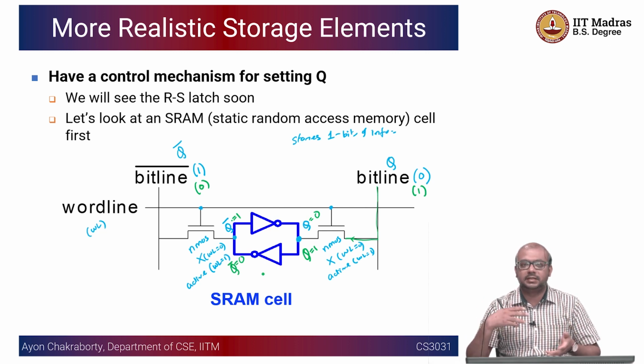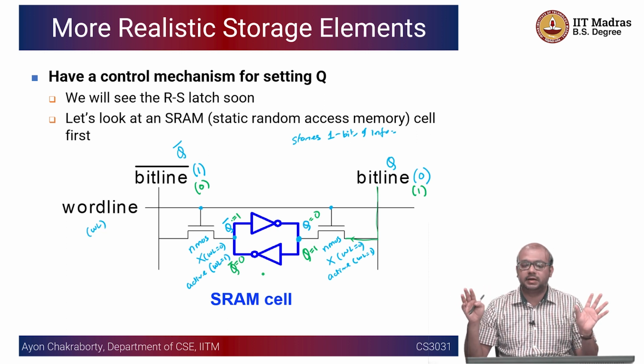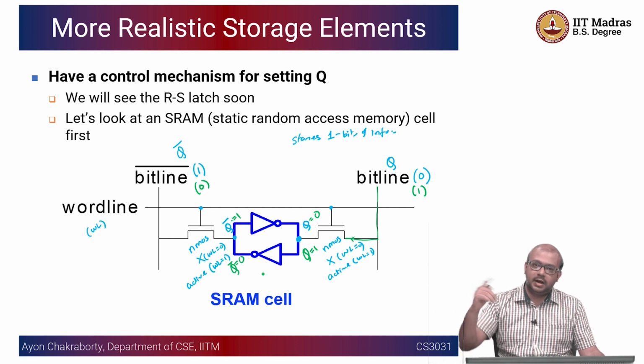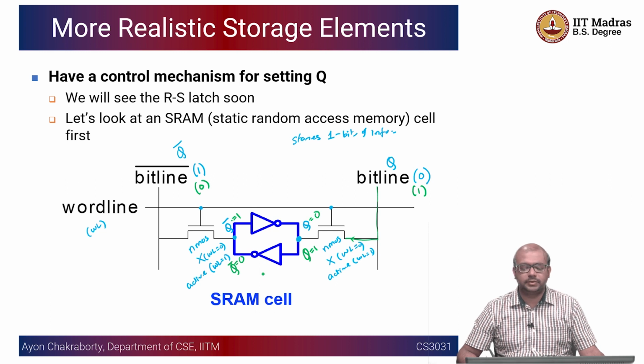If I add 3 plus 4 is equal to 7, next time I add 6 plus 9 equal to 15, 15 has nothing to do with 7. Okay, that was a pure combinational circuit. But what if you have a state, a current state that actually is dependent on the previous set of your outputs? Okay, one example, very simple example that all of you have come across is called a counter.